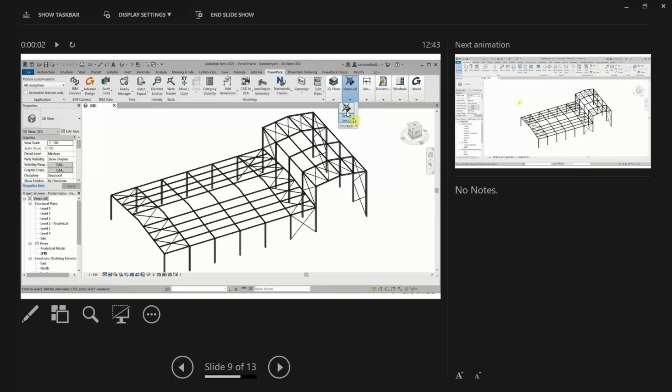In those instances, you need to model up to scratch to make sure it's actually structurally acceptable. So with the Power Pack in Revit, detect those errors and use the following tools. You can see here, we can reset the analytical model, we can trim or extend, and also stretch to any nodes. So it's very important.